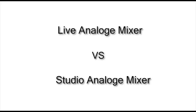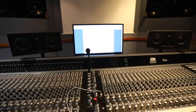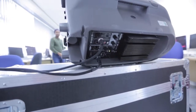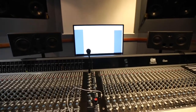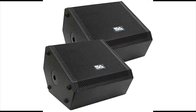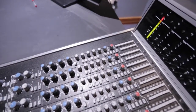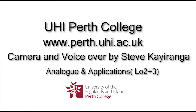When comparing the difference between a live mixer and an analog studio mixer, one will find a difference in monitoring capability. Especially, live mixers have the front of house speakers, whereas in the recording studio, you'll find the stereo monitor speakers. And also, a live mixer's aux sends provide a copy of the signal to the floor monitors for singers and musicians. Whereas the aux sends in the recording studio's mixer are used to send a copy of the signal into the musicians' headphones in the live room.